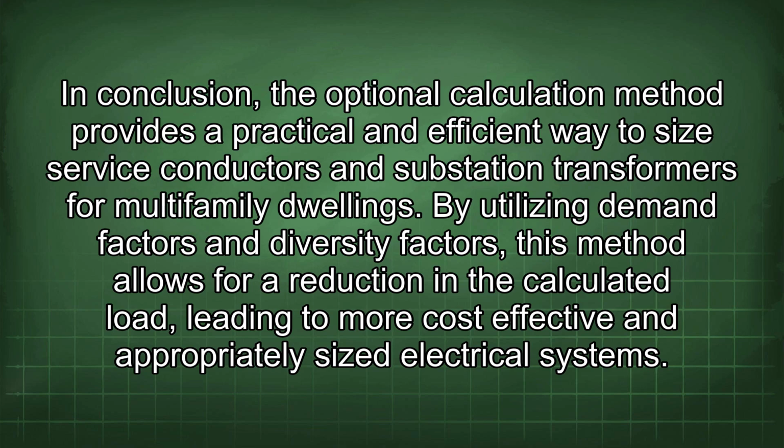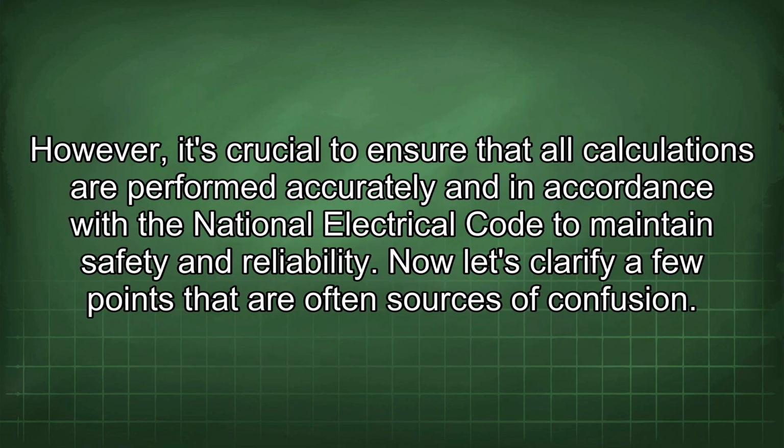transformers for multifamily dwellings. By utilizing demand factors and diversity factors, this method allows for a reduction in the calculated load, leading to more cost-effective and appropriately sized electrical systems. However, it's crucial to ensure that all calculations are performed accurately and in accordance with the National Electrical Code to maintain safety and reliability. Now let's clarify a few points that are often sources of confusion.